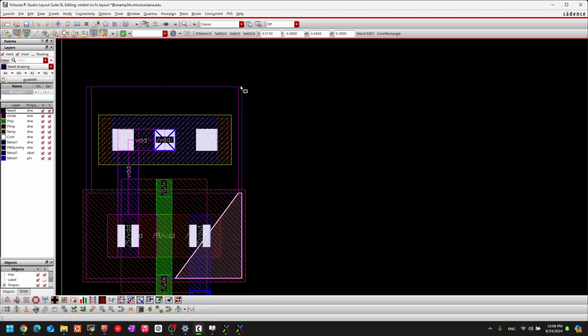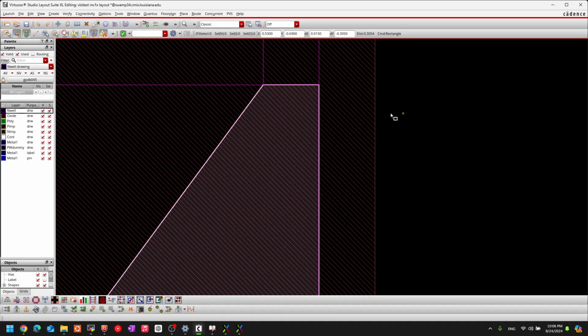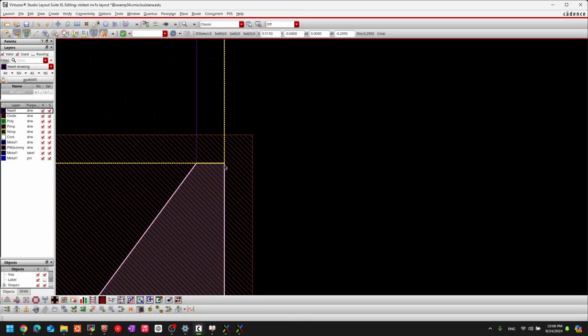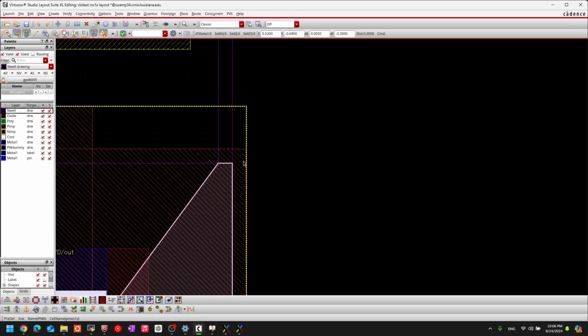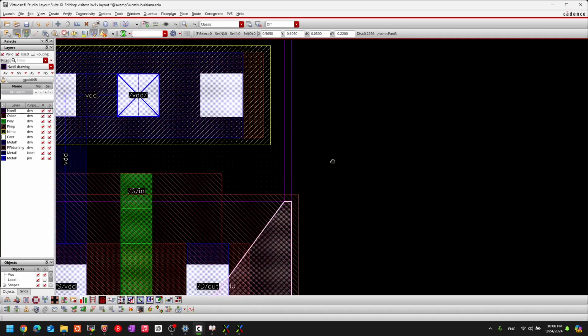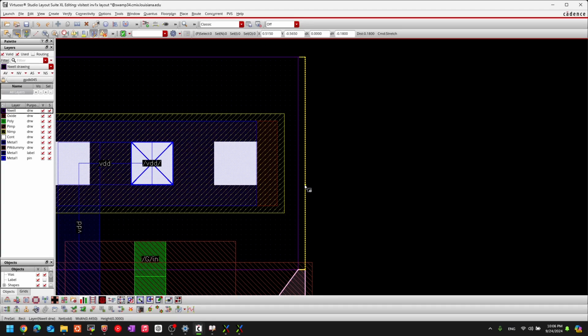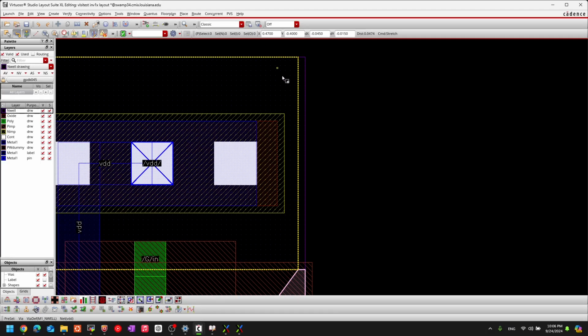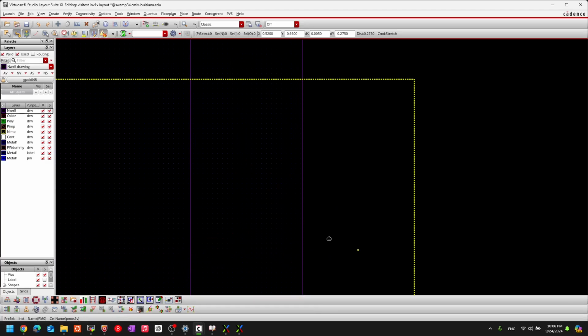Adjust so that you have a perfect rectangle that covers or encloses the upper rectangle. And then double click. Are we beyond this line? Did I align them correctly? Even if I didn't align these lines correctly, what you could do is press S for stretch. And then before clicking on anything, just make sure you're highlighting one line of the object rather than highlighting the whole square. So we could do this.